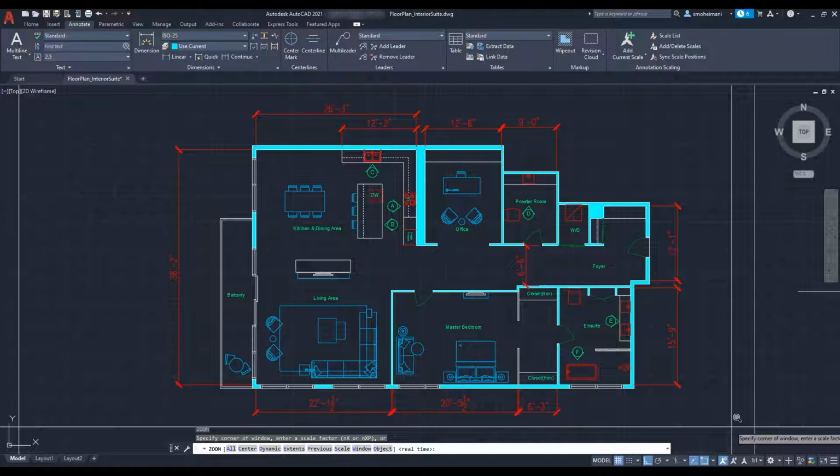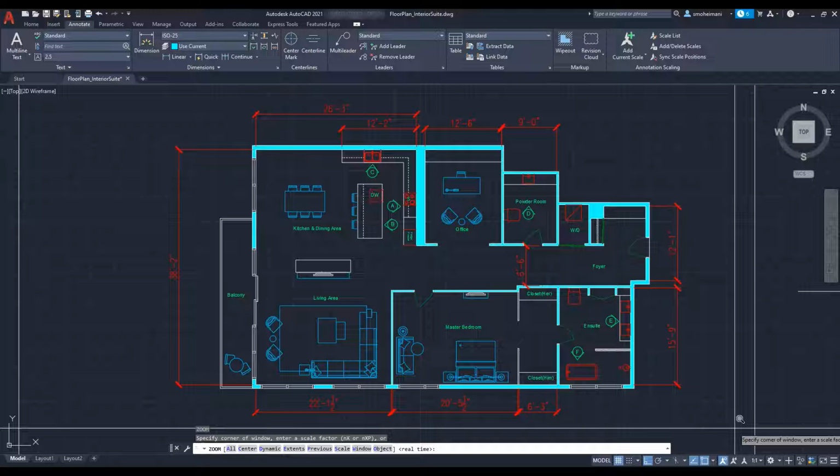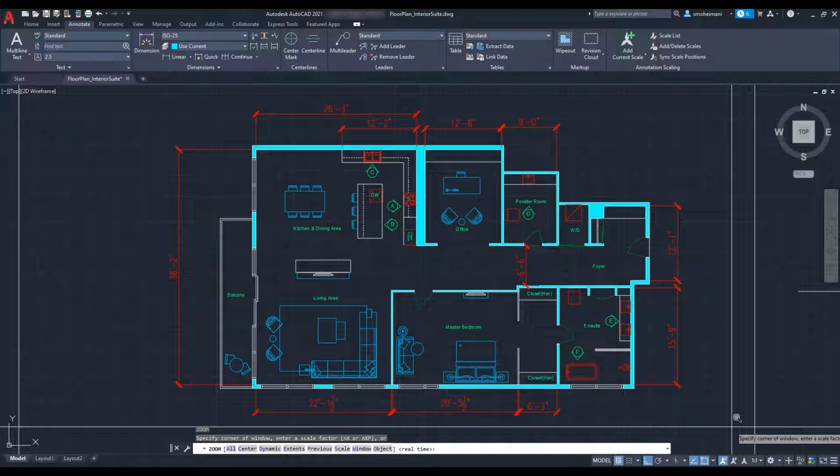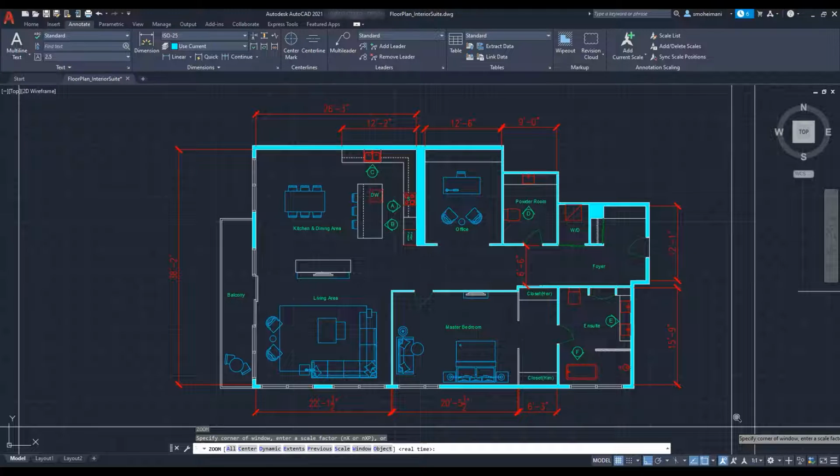Most of the time, our projects start from CAD drawings that we receive from clients, and usually CAD files have a bunch of information and details that aren't necessarily helpful for us as designers. It's always good to keep them as a source, but we don't need to export them to 3ds Max because things like dimensions, text, labels can't be shown in 3ds Max. Meaning, we have to clean up the drawing, leaving only the information necessary to create our scene, such as walls, doors, windows, and the furniture layout.